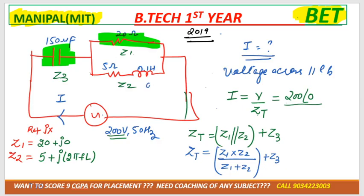By the unit. If they have given you 0.1 ohm, then that would be XL. But they have given you 0.1 Henry, that means they have given you L, not XL. But according to the formula, we need to get XL, right? So as you already know, the formula for XL is 2 pi FL. 2 we know, pi we know, frequency they have given is 50, and L they have given is 0.1. Maybe they'll give you in millihenry, then in that case you need to convert it into standard unit. Plus 5 is equal to Z2.